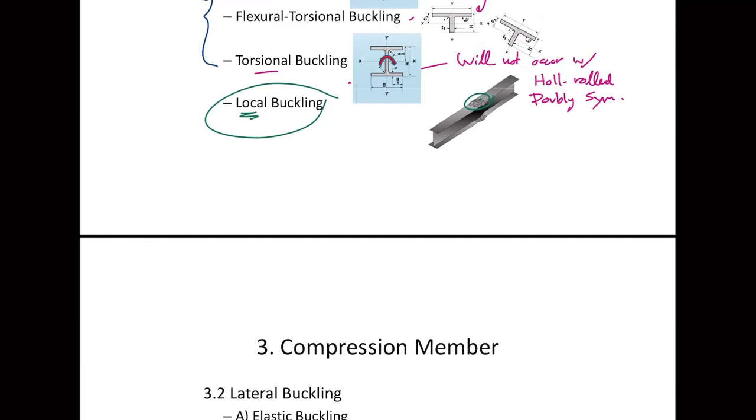But that is one thing. Another thing that you should look at is that it is difficult to have the real pin and the real fix in the real world. If that's what you're asking, because let's just say I want my beam. Okay, now this is off topic a little bit, but I want to create a simple beam. So that means at these two supports, your member must be completely free to rotate, correct? That's your simple beam. So the question is, can we really have that? Or say, I want this. I want both ends to be fixed, you know, just like the fixed moment, stuff like that. Can they really be completely fixed?